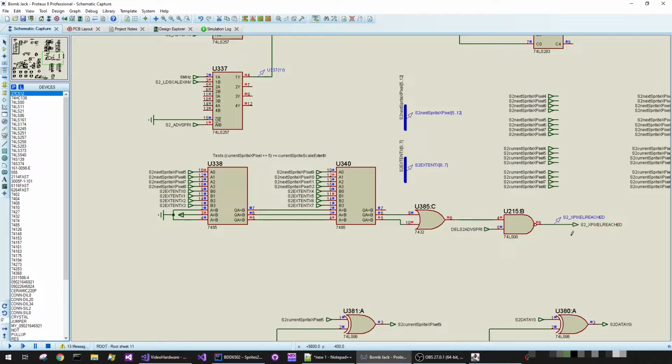So this little piece of logic here was needed because, even though these two comparators are cascaded, I noticed there was some settle time where occasionally it would say that it was equal to or greater than when it wasn't really, and it would happen for a few nanoseconds. So I wanted to filter this out by having the test only done on the high of the sprite value inside the sprite sequence.